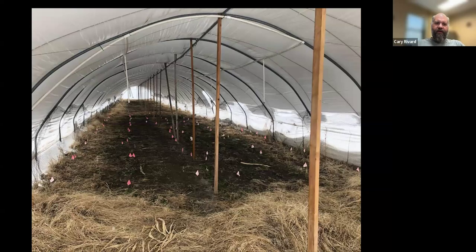This is our four-season tunnel. We were using a, sorry, three-season tunnel. We were using it as a four-season tunnel. There are no trusses on this tunnel. It's not built to hold a snow load. We were doing a research trial where we had to keep this stuff covered over winter. And so we got creative and just put some two by fours in to hold that vertical weight. And you can do that type of thing. I've also seen greenhouses that have structure, like big H bars that basically attach to the bows and hold that vertical weight as well. So there are things you can get a little bit creative with. Just keep in mind this is not ideal. This is something we do in a semi-emergency situation, right? We don't want to plan for this.